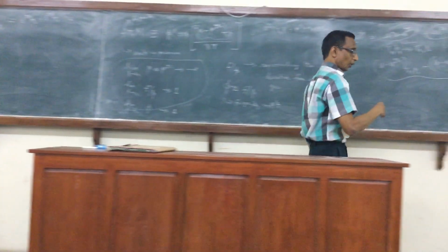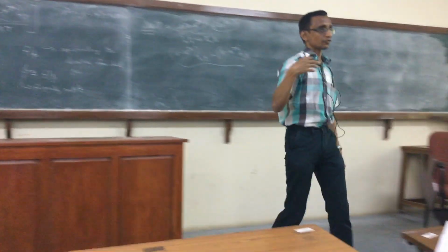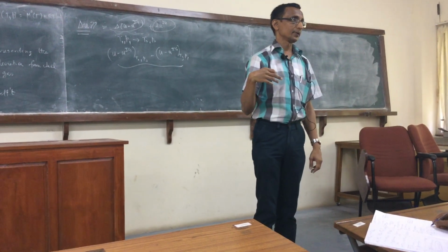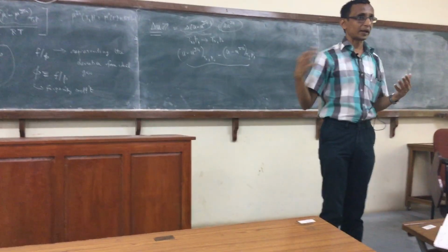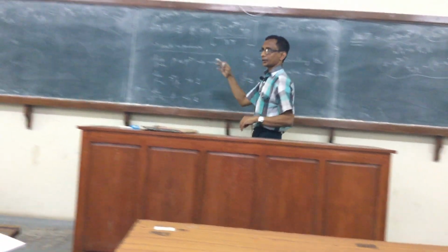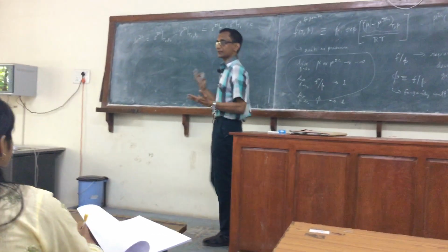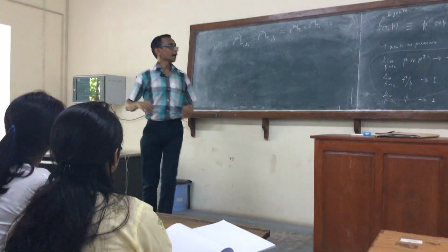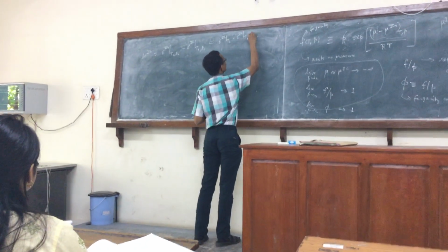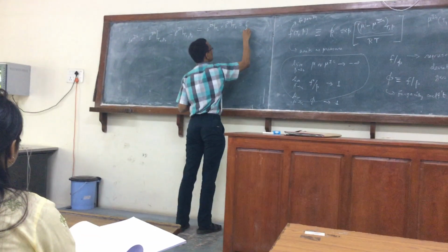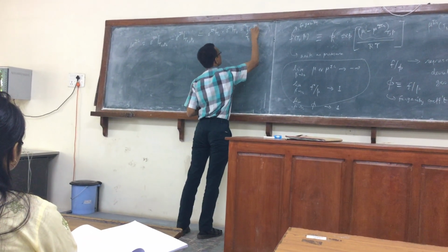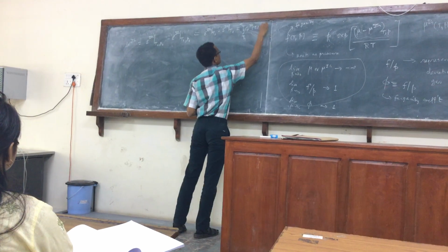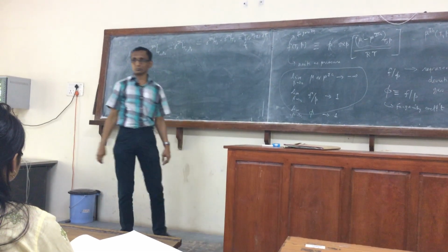Right? So if you have a change of state of the actual substance that involves no change in temperature, that's a special case of the changes we have considered. Then the corresponding internal energy change for the ideal gas will be zero. And this can clearly be written as an integral from T1 to T2 of Cv, which can in general be a function of temperature.